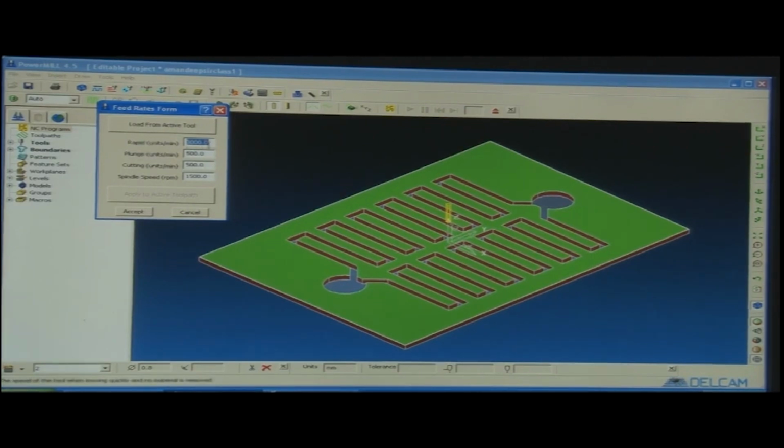Rapid mode is when the tool is coming from a far distance close to the workpiece. Anyway, when we talk about machining, the economics of machining also comes into play. We have to get our machining done. Number one factor is quality. The quality has to be there, that is why some roughing or rough cut is there. After the rough cut, we do the major cuts, known as the finishing cuts. So, we have rough cuts, then rastering, then finishing cuts. Economics of machining is also there. We cannot put more time into machining whatever could be done in less time. We always have to optimize the time for machining.